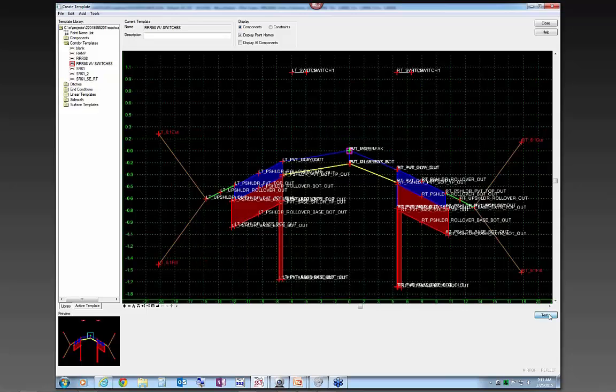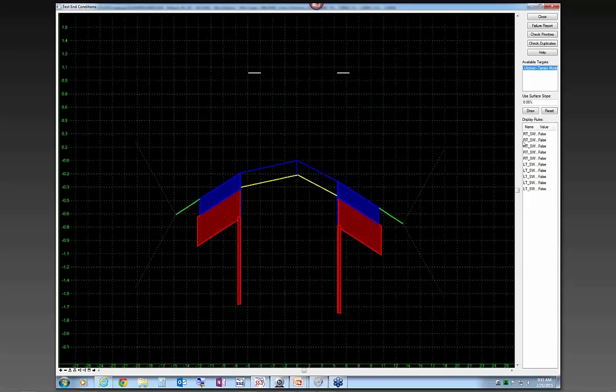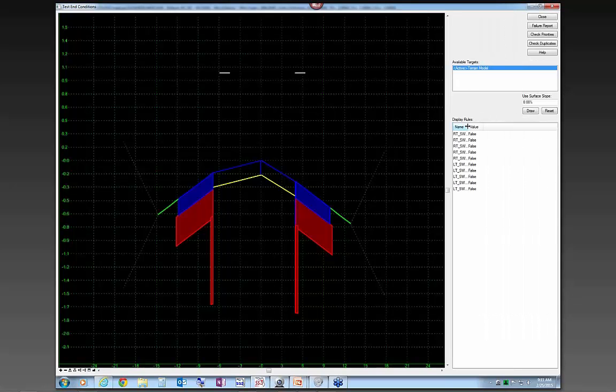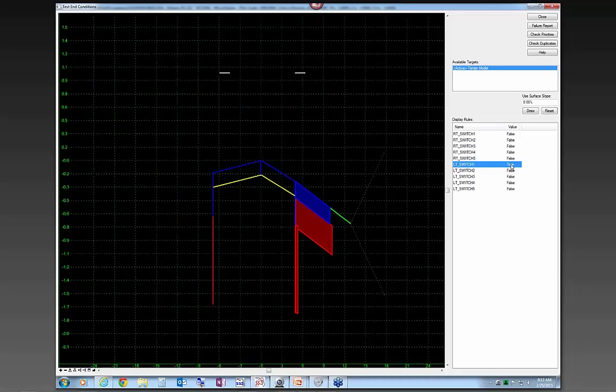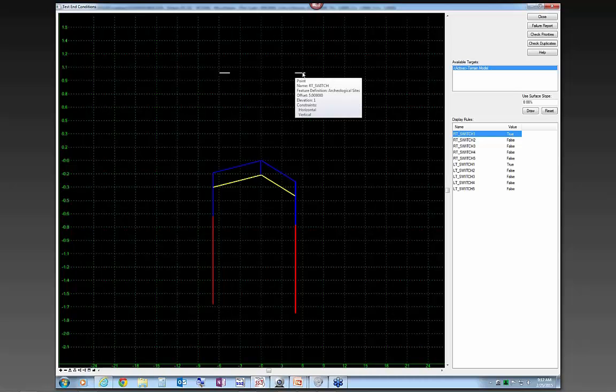And so if you test it and go to these values here, and we went over this in the corridor template design, if you set the value of the switch to true, in other words, if the switch value is 1, then this won't turn on. And the same thing with the right switch. If that value is actually 1, which is the distance between these 2 points, which I can control with a parametric constraint, then it turns off those intersections.